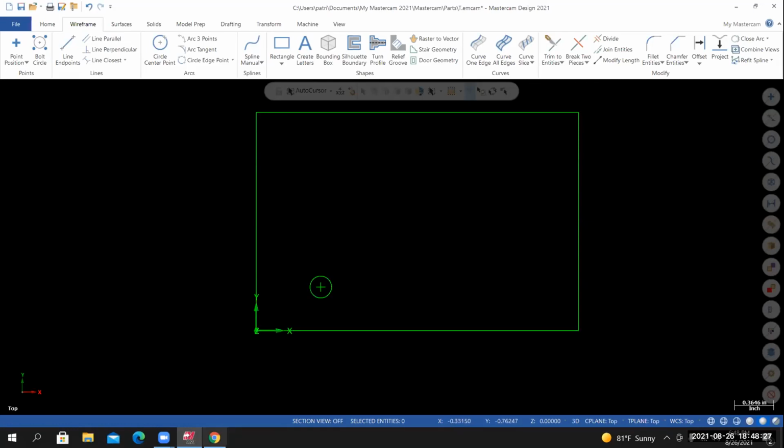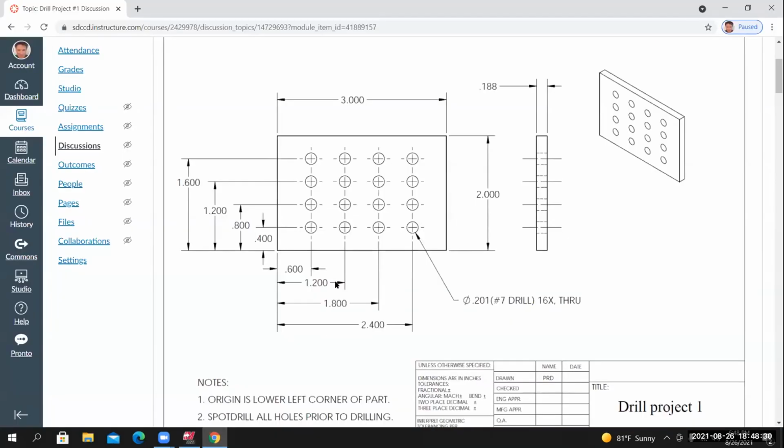All right. I'll go back to the drawing. Now we could place points at the other 19 locations using the same method. Go create the point, identify the XY coordinate, and work our way around and place these additional 19 points. That would be good practice, but it would also be terribly inefficient. I'm going to use a tool called Transform Copy to create three additional instances of the point and the circle